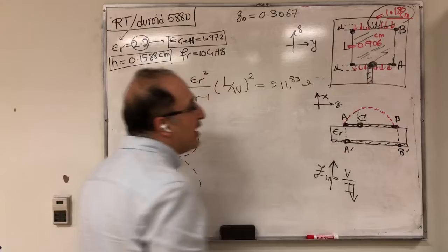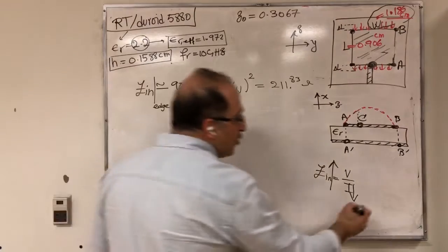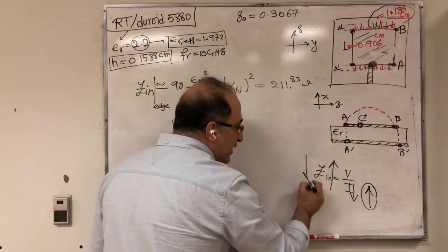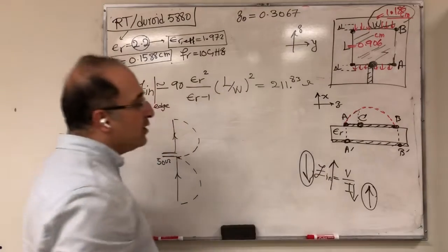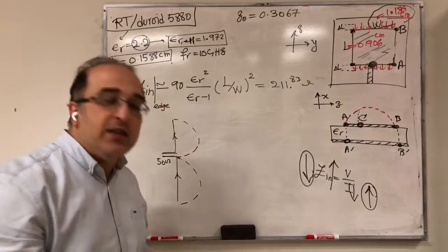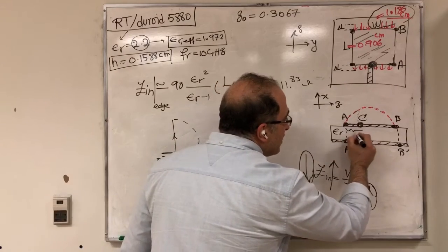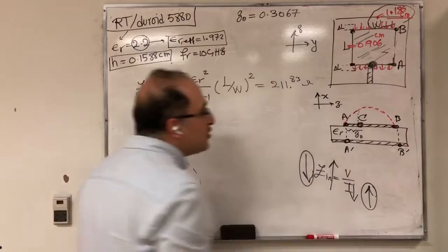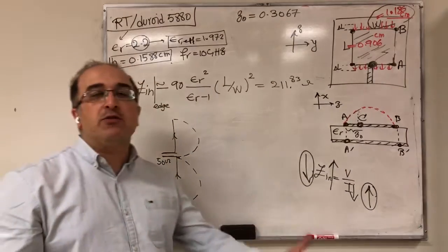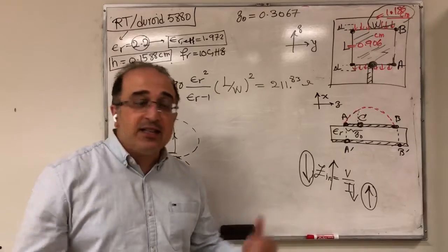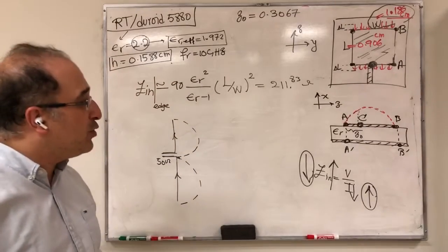So this would be the value of your current. So the current goes up, therefore Z in goes down. And then you can control it until you can just find the value. You can find this position, let's call it Z naught from the edge, so that it's almost 50 ohm, and then you feed at that point. So this is essentially the mechanism to do that.